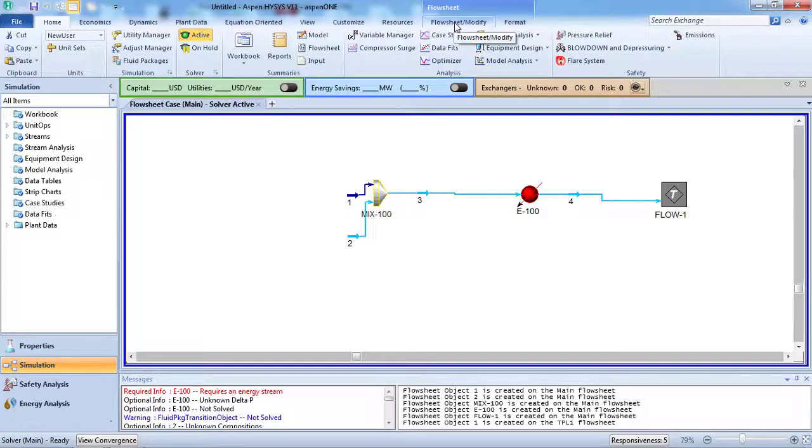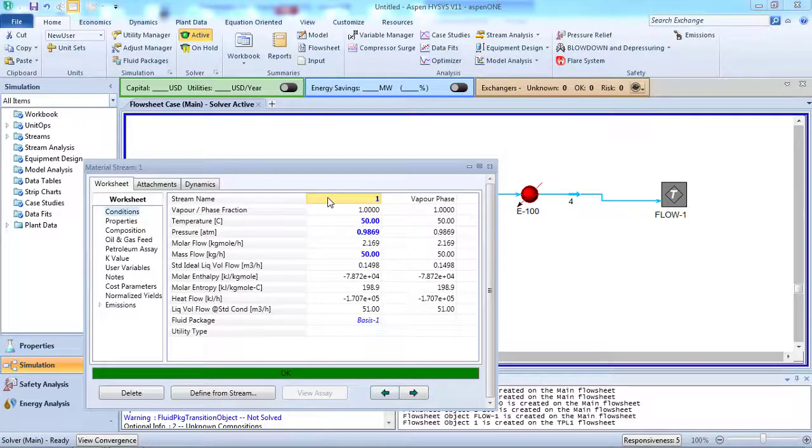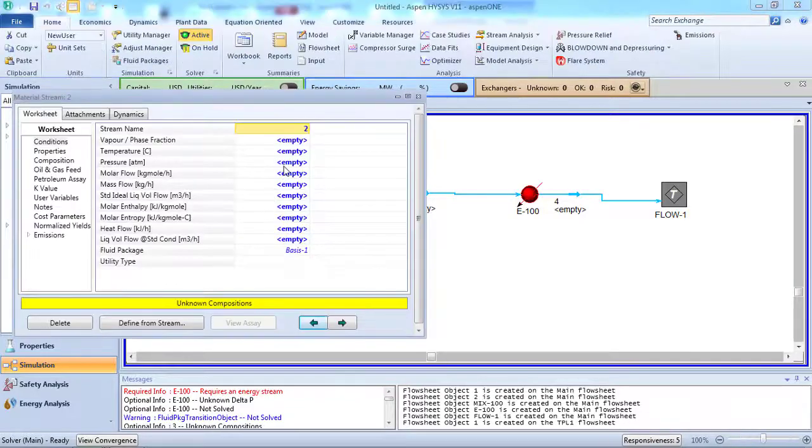From here, from the flowsheet, the label for each stream is its name. It's named 1. For example, I'll name it feed instead of 1. So we have here feed. We can also see the temperature. When you press here, you can see all the temperatures across all the streams. It's not defined, that's why you cannot see it.